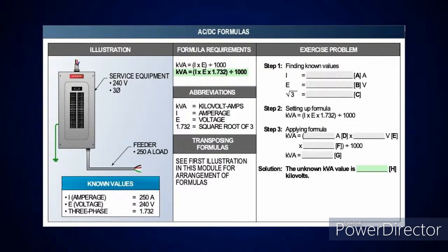And actually, if you go back and look in the American Standards Handbook, and we might do that after we get through all this, we actually show where they would say for a number 14, once you got to like 65 foot or something, they wanted you to start looking at doing voltage drop.